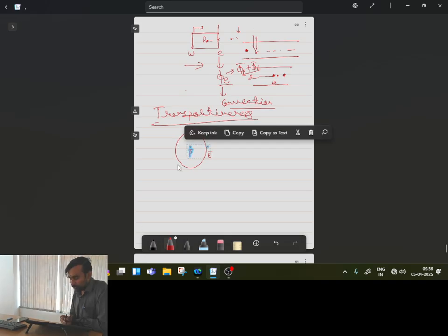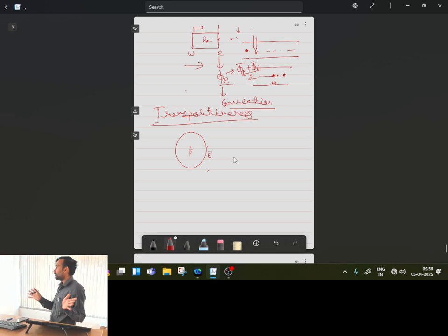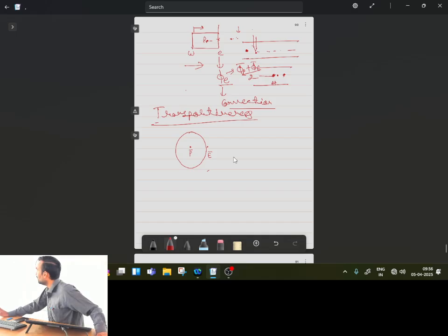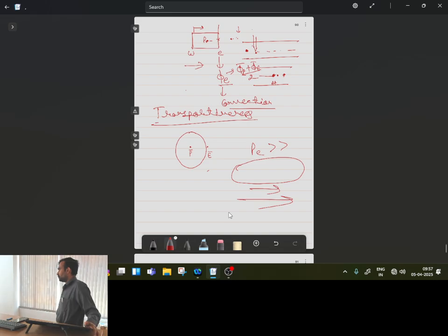So when both are approaching with the same pace, then consideration of dependence on both the parameters will give the correct formulation. But if the Peclet number is very large, in that scenario convection will be dominating, so information will be propagating purely in one direction. The effect of diffusion will actually vanish.